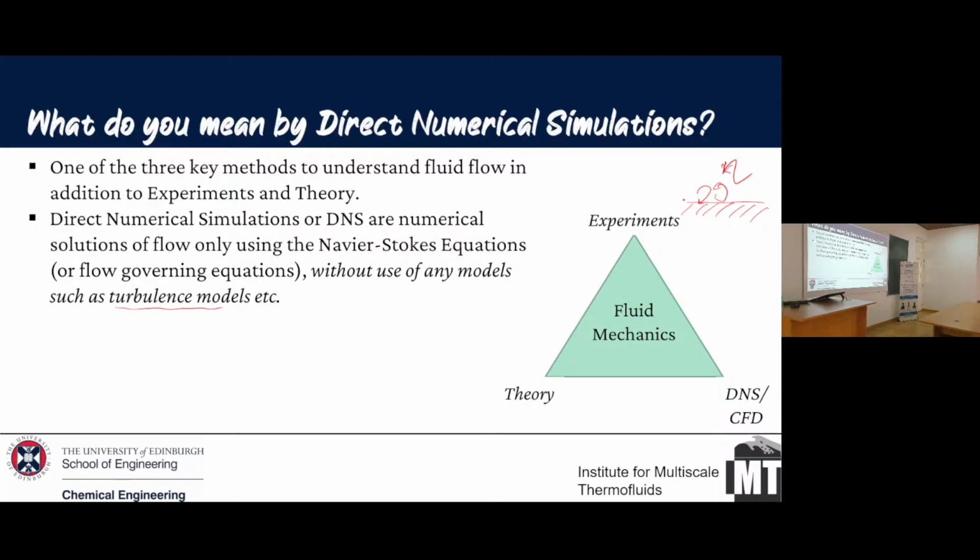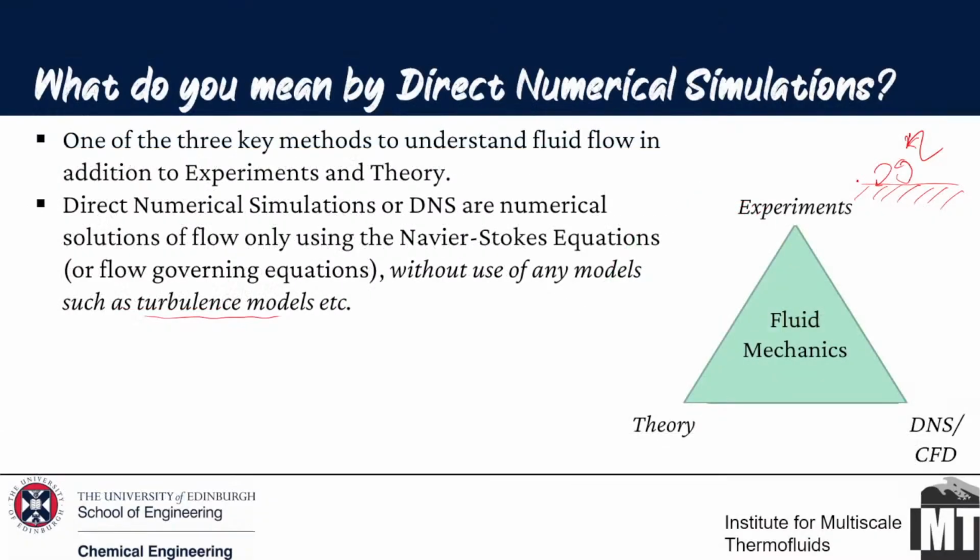K-epsilon, yeah. If you go to industry, the first thing they do is use K-epsilon, or K-omega, or whatever. It's the favorite model. K is basically the strength of the turbulence energy, and epsilon is the dissipation rate. Okay, dk by dt. But the thing is, the problem with that K-epsilon model is basically you're actually, when you